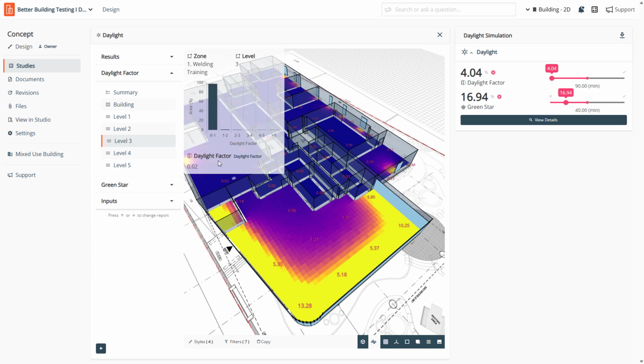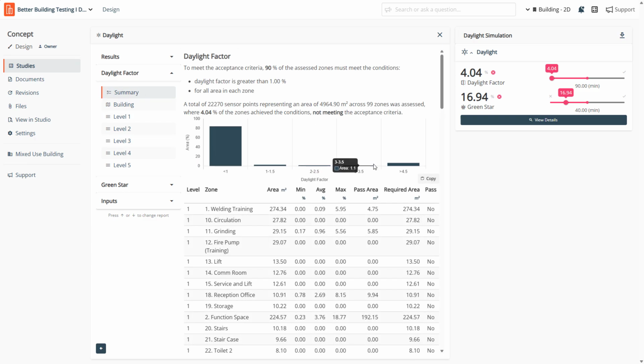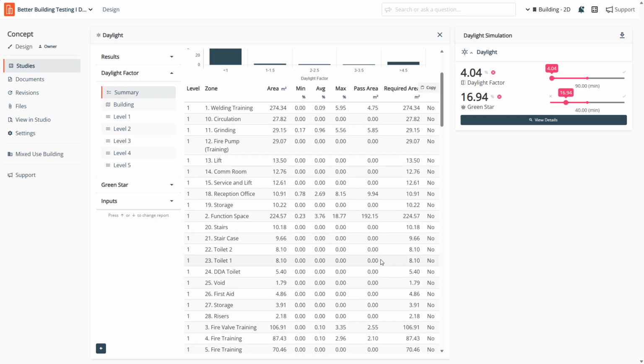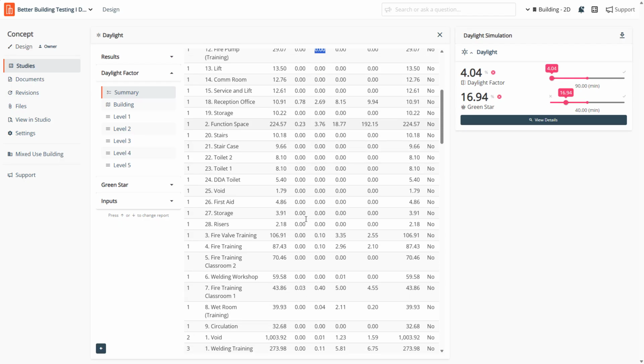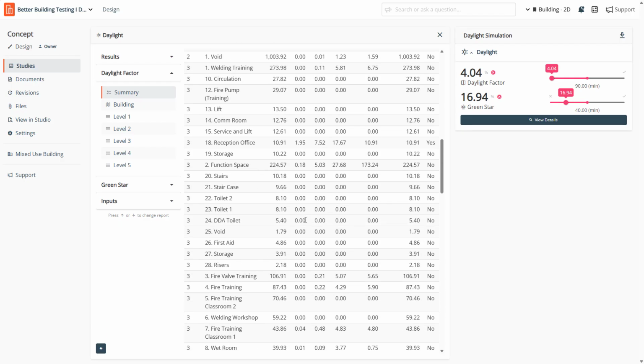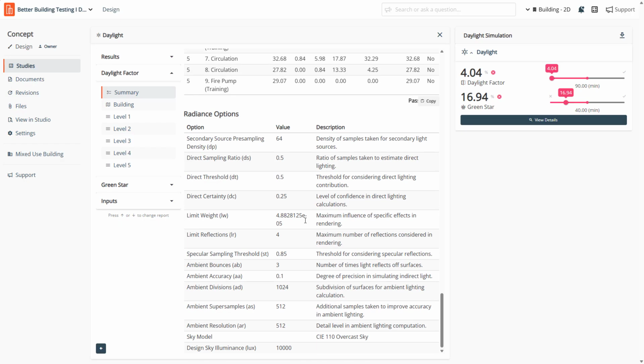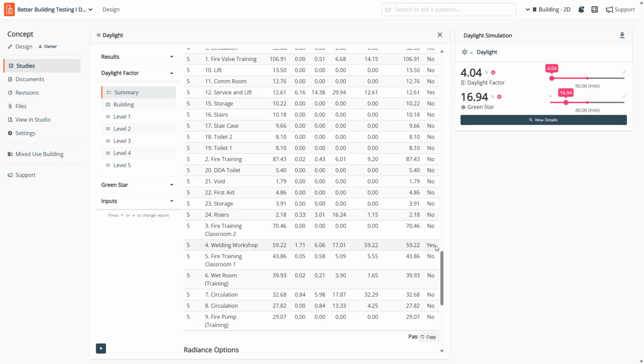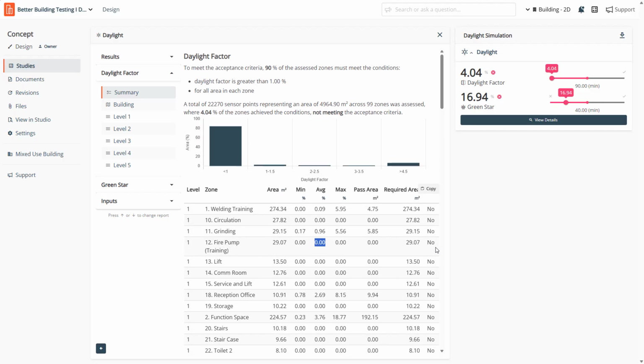But yeah, nothing else to really report there, other than we have lots of failed daylight factor assessments, given that we were looking for an average that was very high of 1, and we can see that very, very few spaces actually achieve that. And the reason it's saying no pretty much across the board is that we've just got a very low level of daylight in the space.